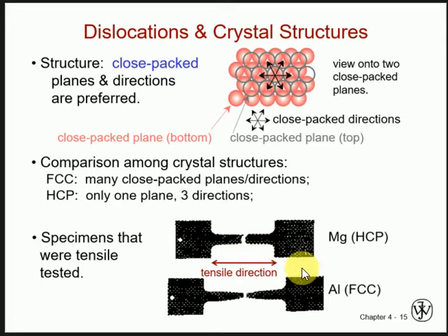On the contrary, aluminium, which has an FCC structure, has a lot of close-packed planes and directions, or high density planes and directions, so this can be deformed easily, and it can be deformed to many percent of the material. So it's more like if this material is rolled or extruded, it is easier for this material to deform, roll or extrude, but this material cannot be deformed much. So its deformation is more possible, its deformation cannot be much, and this depends upon the crystal structure.